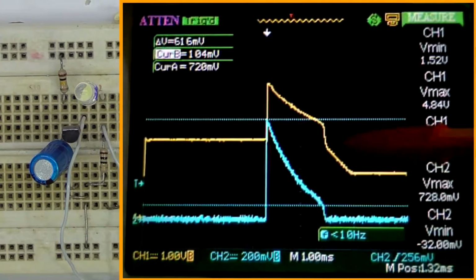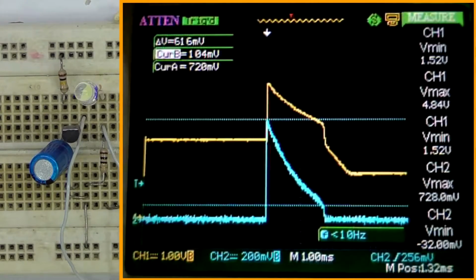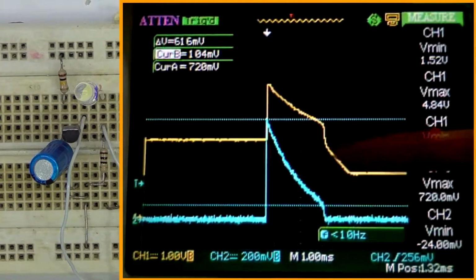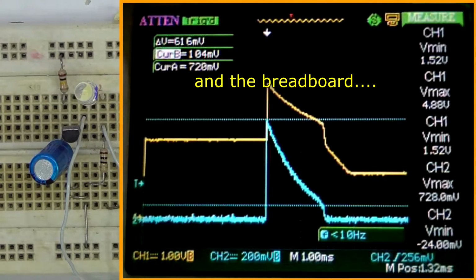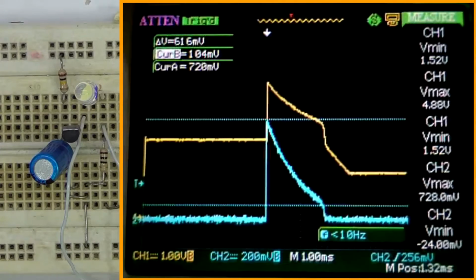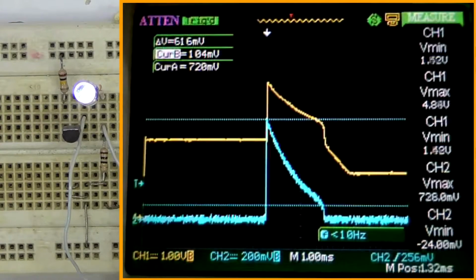And so there's that little discharge trace there that we saw before, and you can see it's clearly after the current. So this must be some sort of capacitance of the transistor itself, and because the load is switched off, it's probably measurable in the picofarads, I would expect. Interesting. So another experiment we can do, I'm not sure how many of those flashes we're seeing, is changing the capacitor.